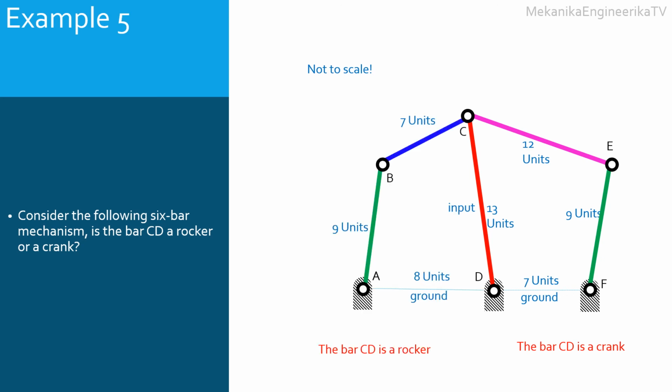Analyzing the ABCD 4-bar mechanism leads to a rocker CD bar. On the opposite, analyzing the DCEF 4-bar mechanism gives CD a crank. However, the rocker motion of CD leads to a harder constraint on CD motion. The rocker motion prevails over the crank motion. CD is here subjected to the hardest condition. Thus, CD here is a rocker.